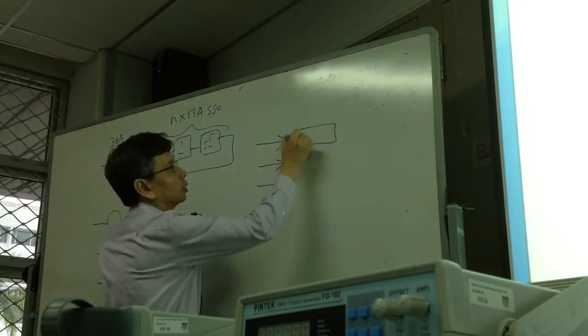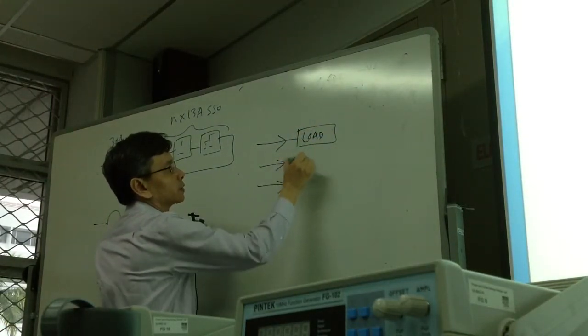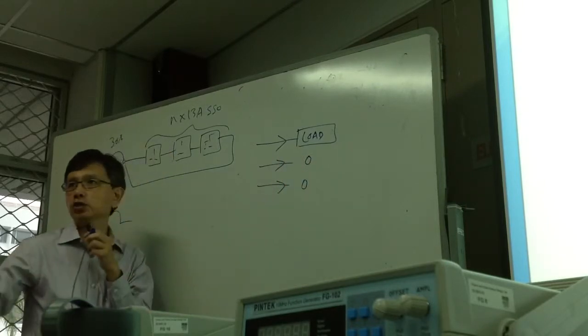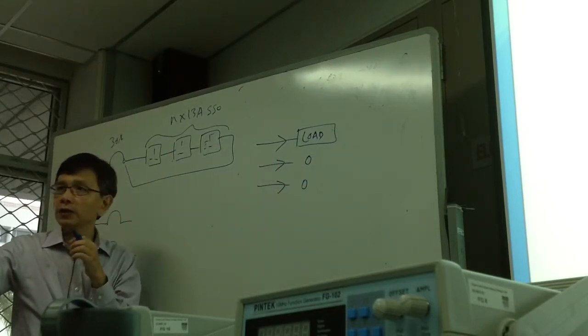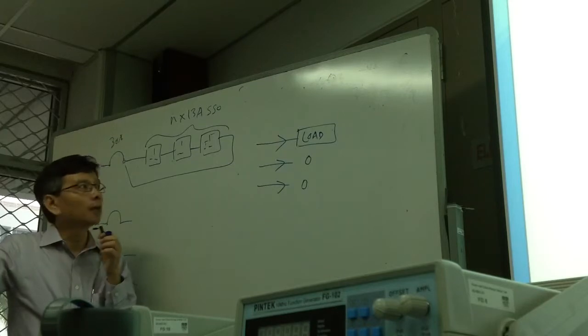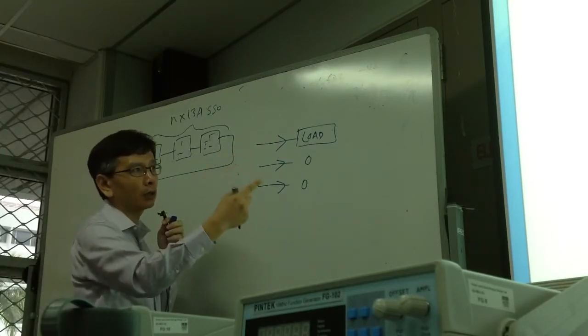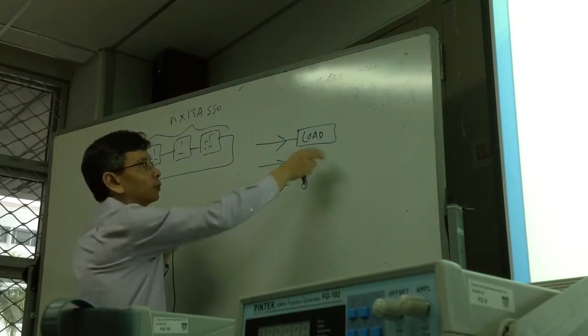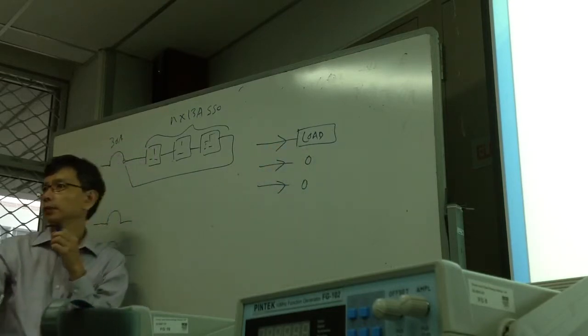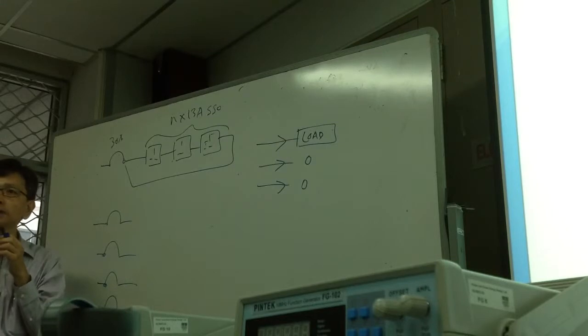supplying all on one phase. Okay? If I have three-phase situations, it has to be three-phase because I did a three-phase aircon. But for the single-phase load, which is fluorescent light, socket outlet, and the standing fans, I can put them all in the same phase. Correct?